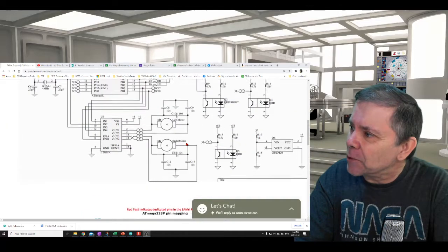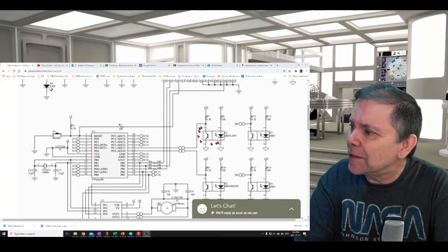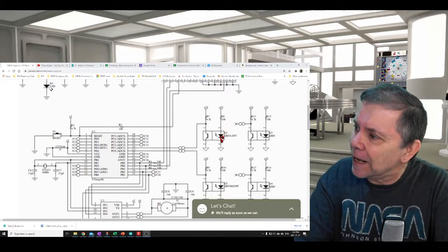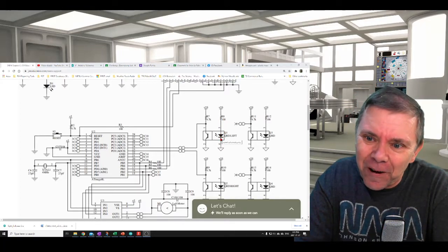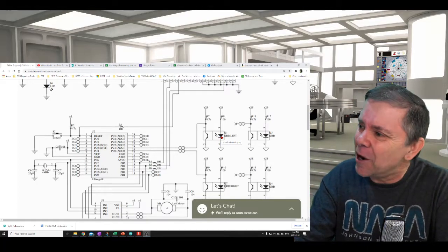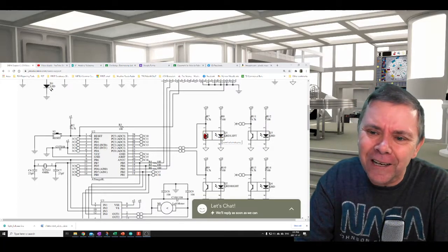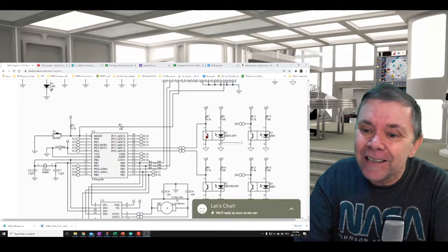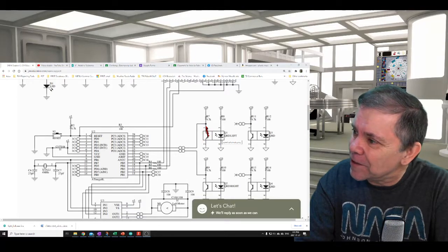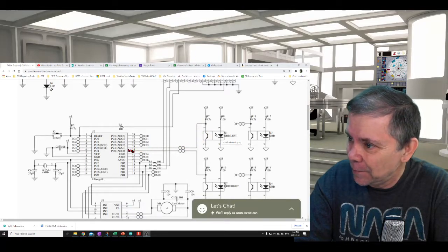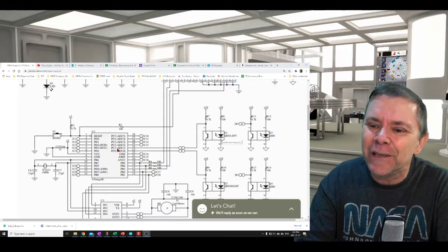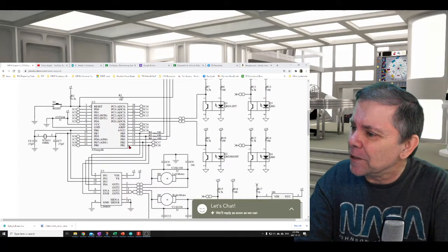If you want to look at the actual schematic, you can see the sensors right over here. Now the sensors consist of two parts. They consist of a down-facing infrared transmitter, an LED that just shines downwards, and a photo detector here, a little photo transistor that is looking down at the reflection. And this photo transistor is hooked up to PC1, and the other one's hooked up to PC0, so you can see they're just going into the microprocessor.